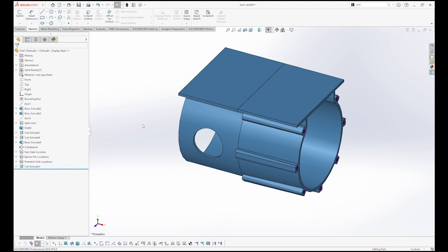And our EDM machines are capable of producing an EDM fine surface finish, which typically lands at SPI standard D1 and D2. This finish is a smooth matte finish. It's included as a standard finish with no upcharge. And a lot of the projects kind of land in that direction.